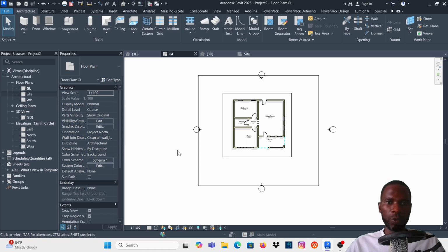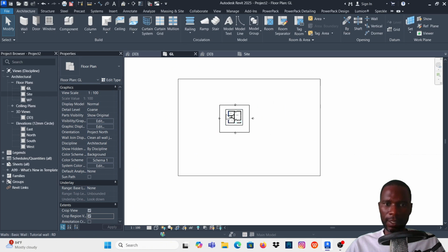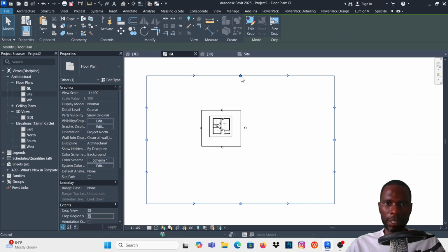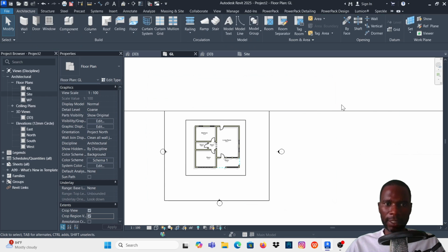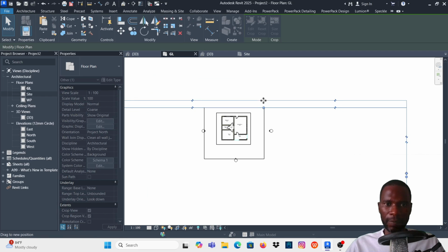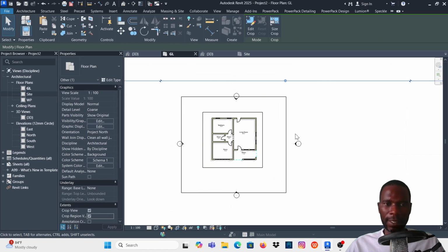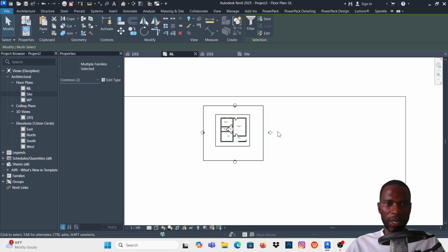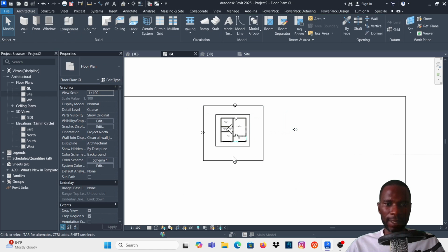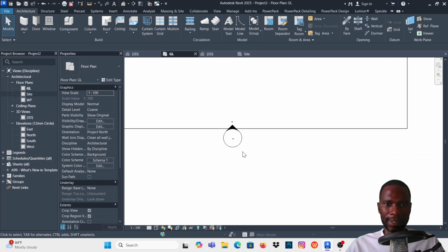Now, if you want to remove this box, you can simply select there. Actually, make sure that this is activated. Where is it? Oh, it's actually very, very big. You can drag it up to somewhere here. Actually, let me not cut these. These elevation markers, if you want, you can drag by holding your left mouse like that. Then select it.